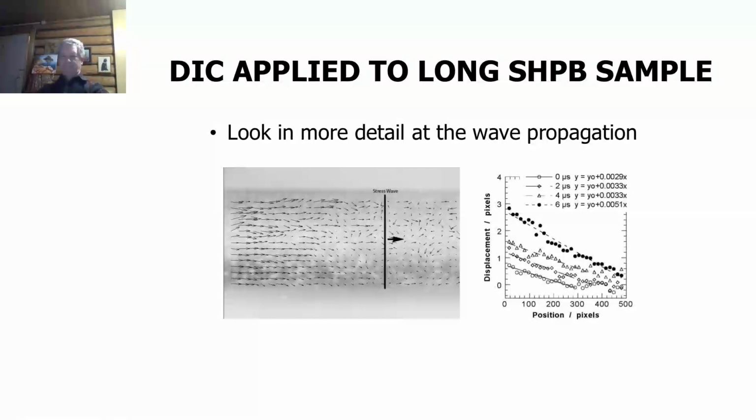So we assumed there's a small temperature rise within the polymer, but we haven't seen it directly. It's of the order of a few degrees. It's because polymer behavior with temperature is not as straightforward as that of metals. You can stretch polymer, rubber bands for example, and they will get cold because of the change of entropy in the system, which is why I mentioned the change in temperature and the change in entropy.